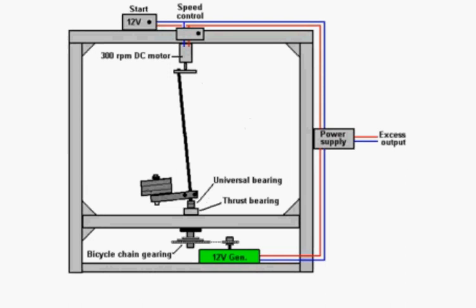But you can put a large weight, say the sort of things that you get as a dumbbell weight, onto an arm, and with a very simple arrangement here, you can spin the motor, and that drives through a universal joint, a shaft with, say, bicycle wheel gearing, that is a chain and a sprocket, to drive a 12-volt or other generator. And probably the best generator to use in something like that is one intended for a wind power system, because that's easy to do as such.